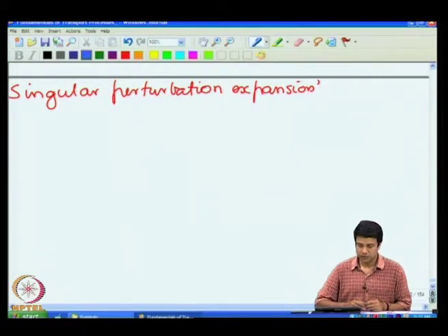Okay. And therefore, one has to postulate a layer of small thickness at the surface, where the thickness is small, therefore the gradients, the derivatives with respect to position, are large, in such a way that there is still a balance between convection and diffusion within this layer.